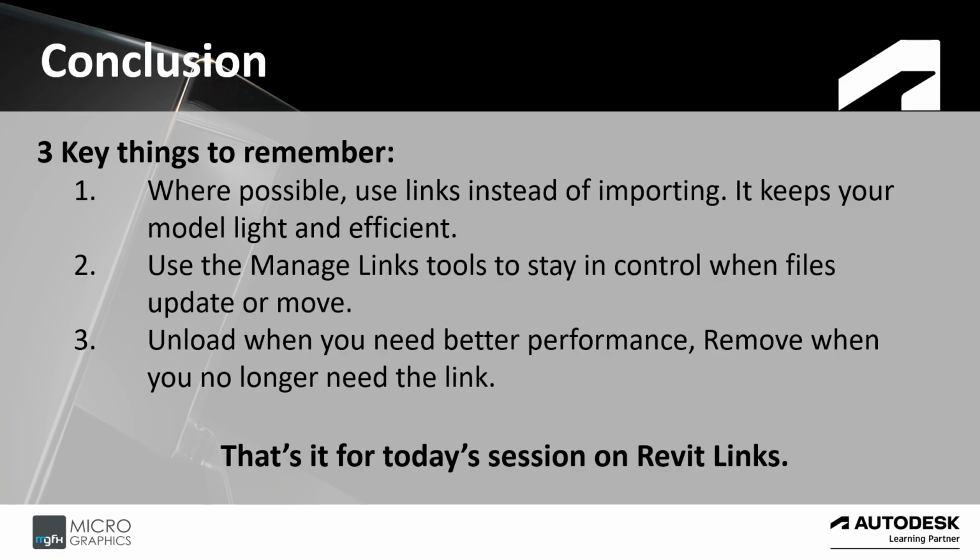Use the Manage Links tools to stay in control when files update or move. Unload when you need better performance. Remove when you no longer need the link. So that is it for today on Revit links for this session.